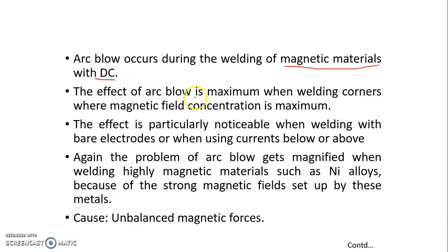The effect of arc blow is maximum when welding corners, where the magnetic flux field concentration is maximum. The effect is proportionally noticeable when welding with bare electrodes.